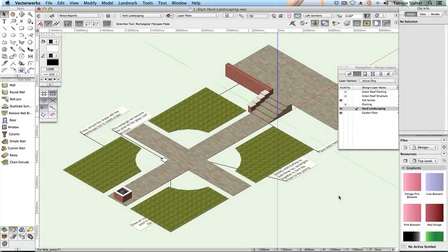Draw walls. In this exercise, you'll draw the remaining wall to retain the other half of the terrace and the steps. You'll also learn how to step the walls so that they follow the incline of the steps, and then you'll model some coping. Use the wall tool to draw walls.